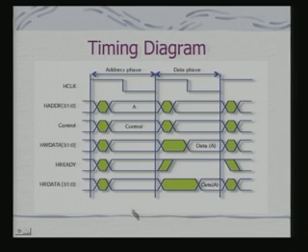Now, this timing diagram is very similar to what we have seen in the context of simple memory interfacing. But the overall transaction definition with respect to the bus, which involves communication with the arbiter and grant signals, as well as the response signals coming from the slaves, makes the transaction much more complex than accessing a simple memory.